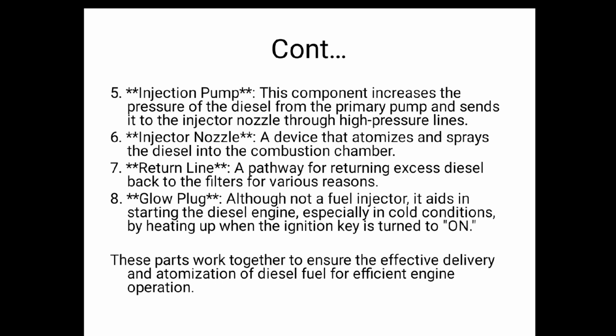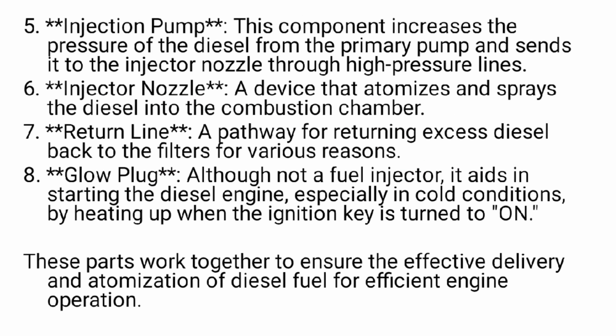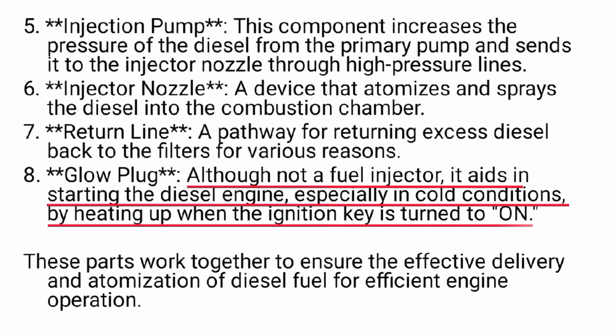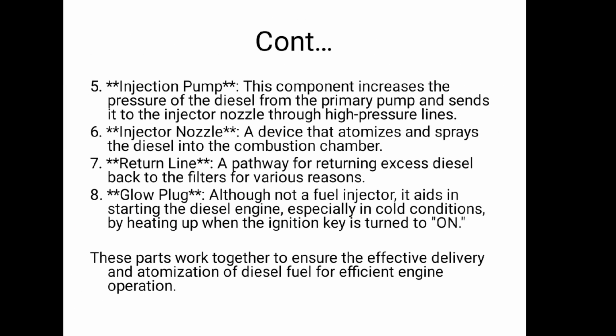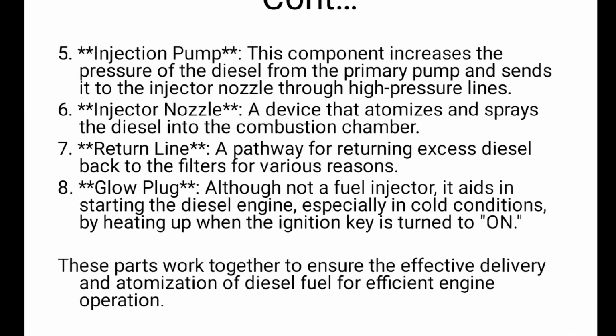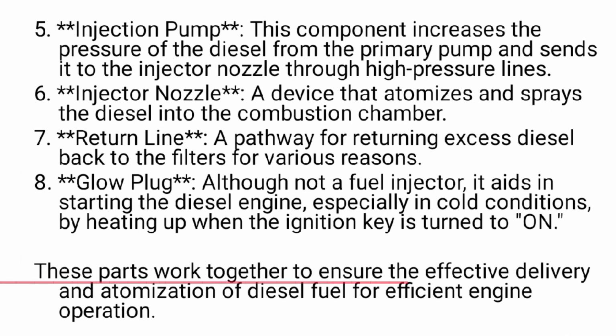And lastly, we have the glow plug. Although not a fuel injector, it aids in starting the diesel engine, especially in cold conditions, by heating up when the ignition key is turned to on. This glow plug is more like a choke valve in a diesel engine, so it has some similarity with the choke valve of a gasoline engine. So these parts all work together to ensure the effective delivery and atomization of diesel fuel for efficient engine operation.